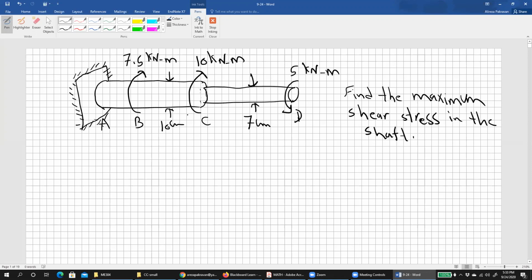So, okay, it's the same as statics. Since we have three torques here, let's first review the formula, maybe you forgot. This is the formula to find the shear stress, right? So R and J could be the material parameters. R is radius, J moment of inertia, and T is a torque. We should find the torque in each section.